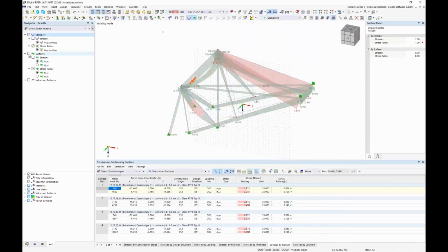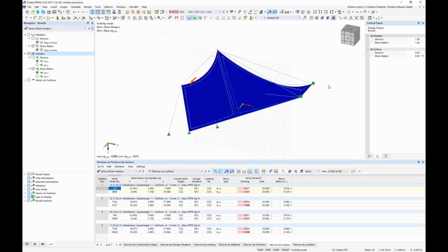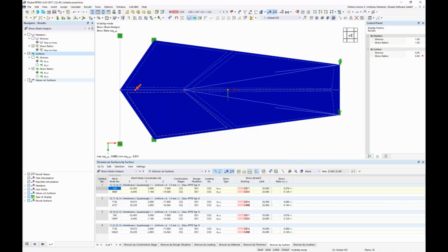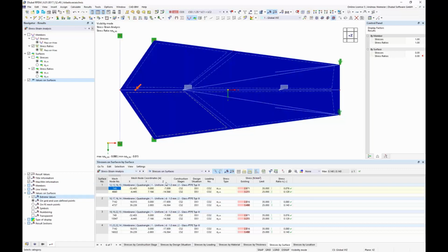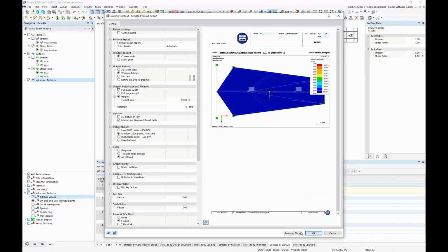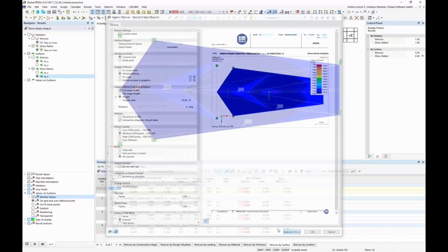And make me a utilization picture of the surface utilization from top view with values on surfaces, maybe extreme values. So everything is possible. You can create your own pictures as expected, and let's go to print and move it into reports. The same for the Y direction, and print, and if it fits we update the report.